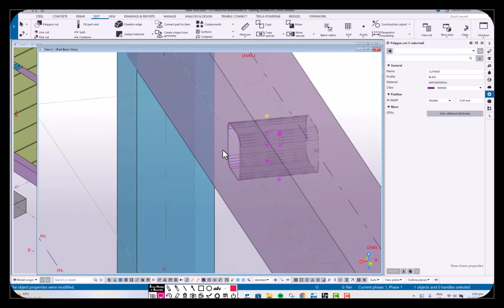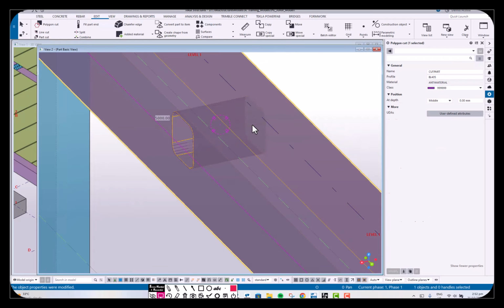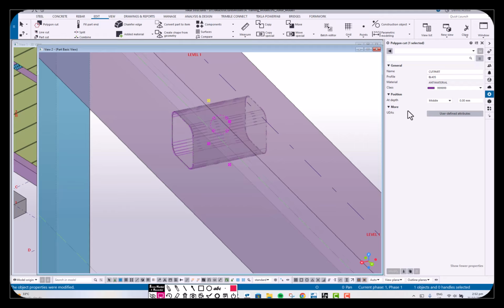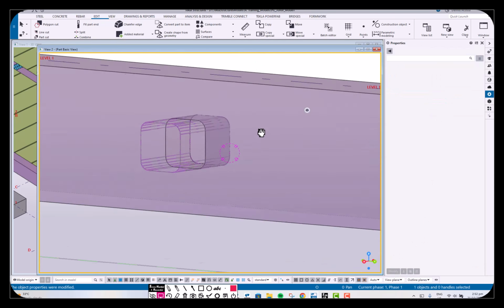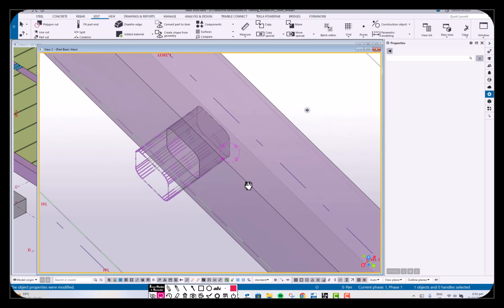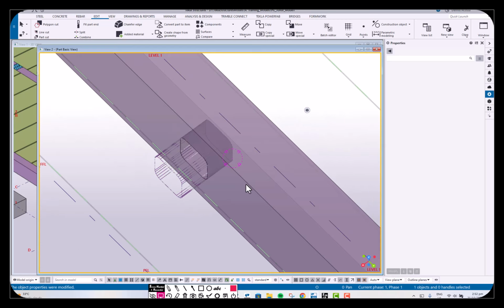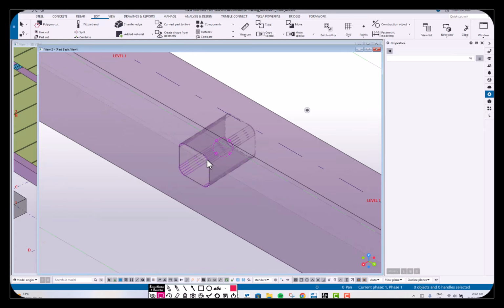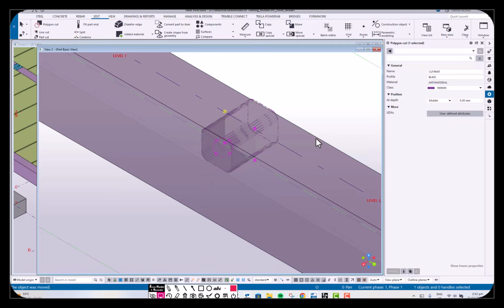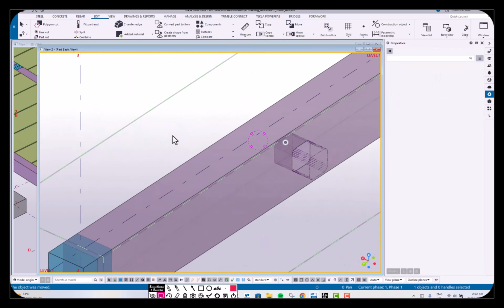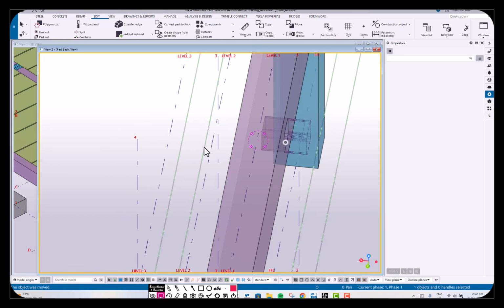So if you want to cut this one halfway only, one thing that you can do is look, select this one, and then you can see here instead of middle, you change this one to front or behind, and then modify. And see, that's it. It's half, right? Or the other one is this. Look, select this. Did you forget that you can move this? Move perpendicular. See? You can also move the cut, by the way.